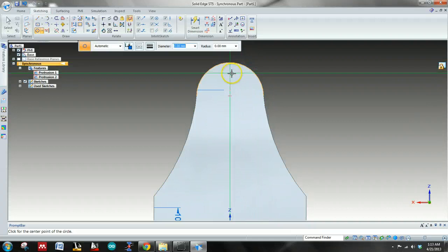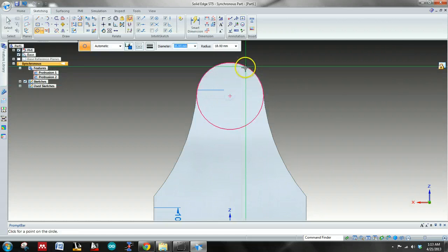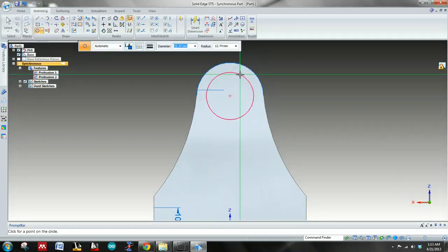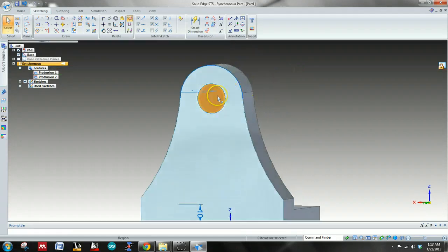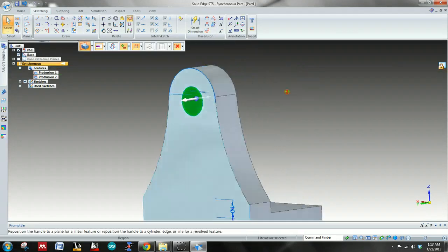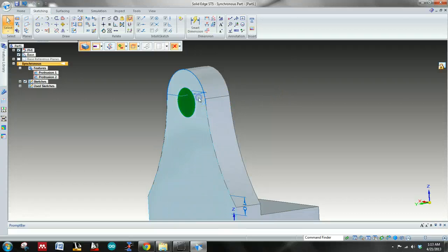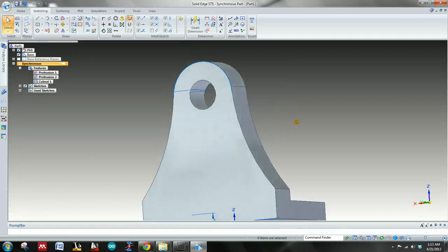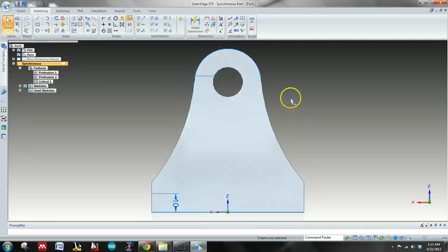This is a trick that you can do right here. This will automatically find the center point. That target right there is center. Okay, click it. And so we don't want to go 36, right? We want to go diameter of 16. Okay, I'm going to hover over this, click it, and then I'm going to just bring it through. There we go. Control K.